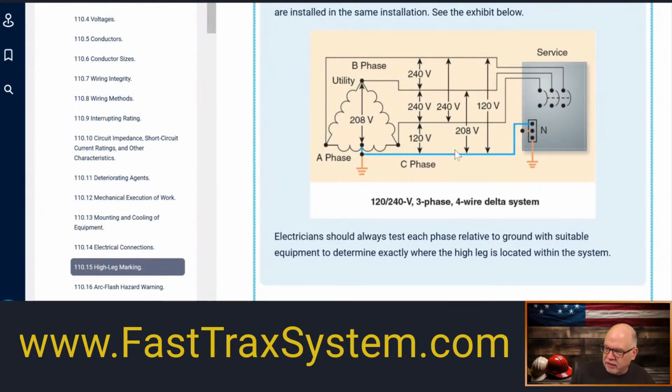So here's your, again, you saw me say it's a 120/240 delta, but you have, in this case, mid windings, and you have the connection made here. So this is your typical A to C phase that we're going to get right here, where they're going to tap the midpoint. But here you see the B. From here to here, it vectorially creates the 208. From here, okay? And so you see here B to here, 208, right? That's that B leg, okay?